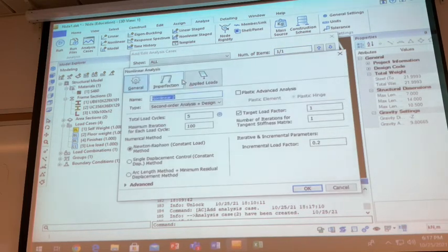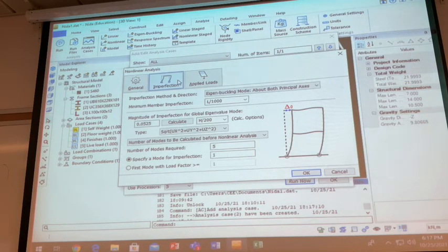And also here, in position, when you base on the linear analysis, you need to apply the notional load and get the deflection. Based on the deflection, you can calculate the lambda critical. Okay, but now when you use the nonlinear analysis, go to the imperfection. Actually, notional load is the virtual load you load up. The limit is this doesn't happen. But you need to trigger the P big delta effect. You need to make this member incline a little bit, tilt a little bit, and then simulate the P big delta effect. Okay, this is the purpose of the notional load.